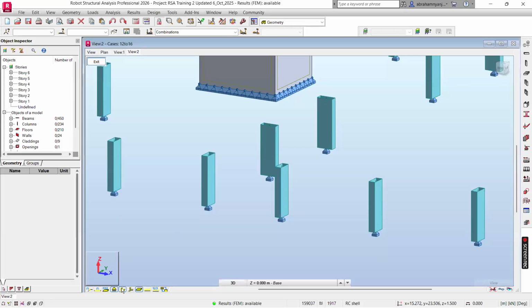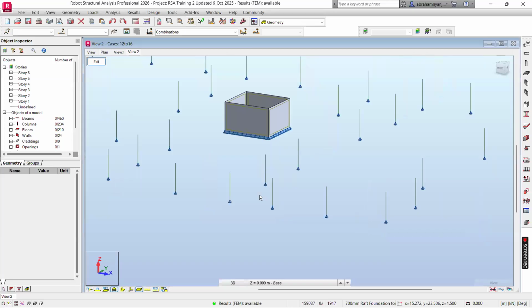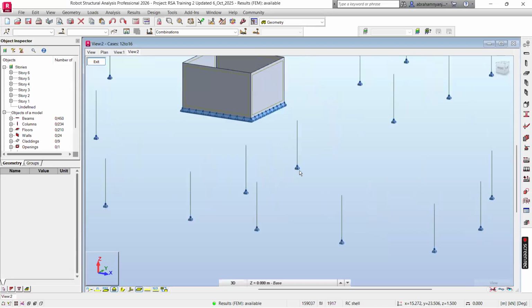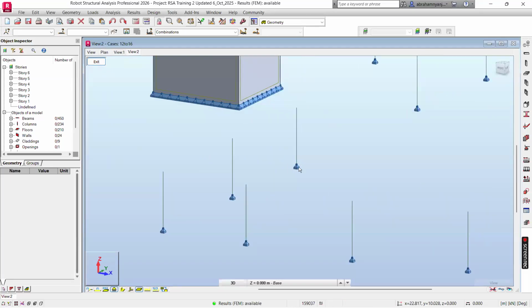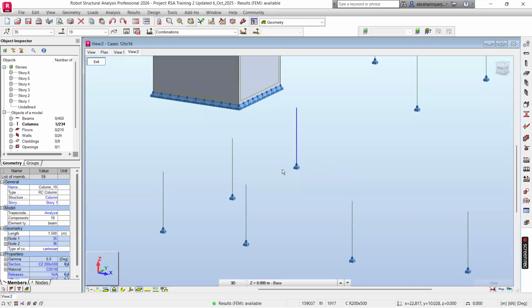I'm going to turn off the section shapes. Why am I turning off the section shapes? I want to extract this node only and leave the column, only the node, because that is where the FZ is. Remember, at first we highlighted from right to left, because when you highlight from right to left, whatever member my selection box touches will be highlighted.